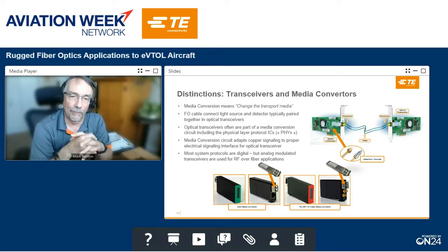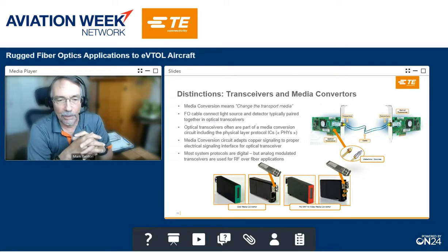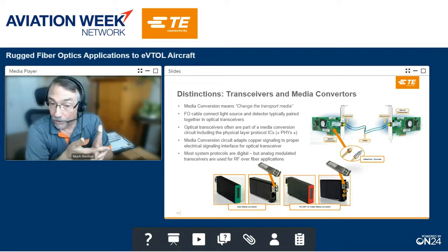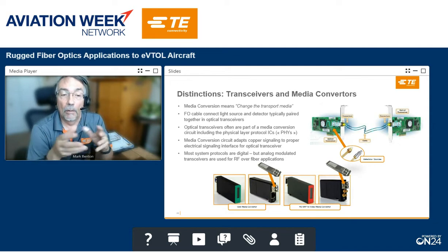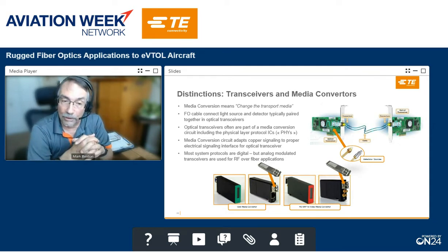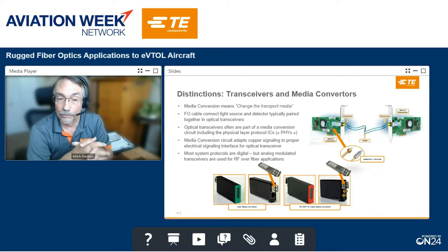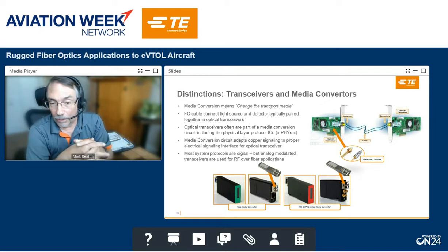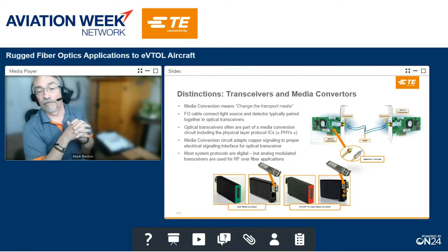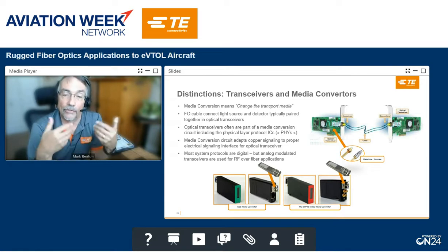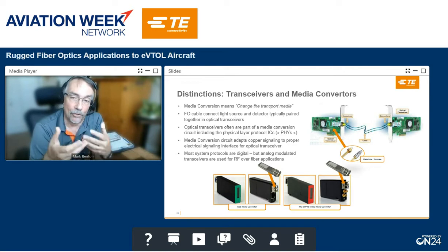So for example, along the bottom here are a couple of examples of some legacy media converter solutions that use standard multi-source fiber optic transceivers for that final conversion. But you'll notice that on the green unit pair to the left, there's an RJ connection cable that brings in 4 twisted pairs of cabling. That gets ultimately translated into 2 differential electrical signals that have to drive that transceiver. The one on the right is a digital video situation, which tends to be single-ended, one direction, 75 ohm coax information, which is not easily interfaceable to a fiber optic transceiver either. And so again, you have a PHY level circuit that does that conversion for you.